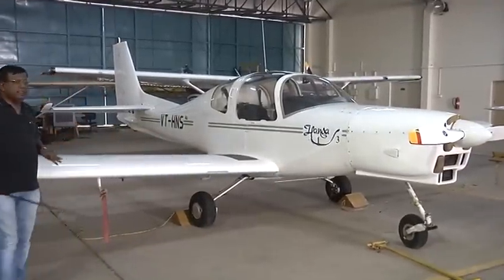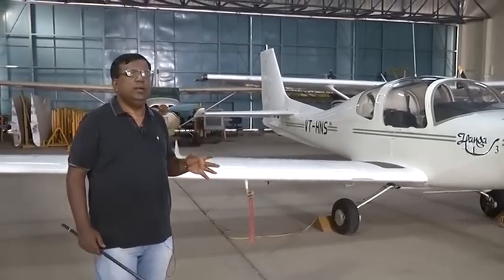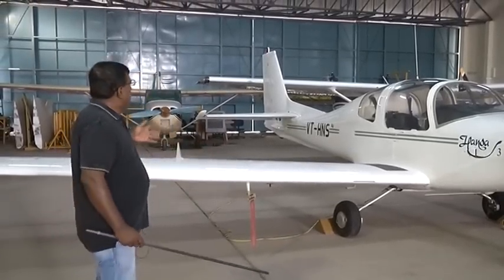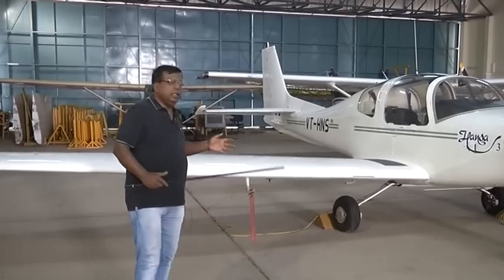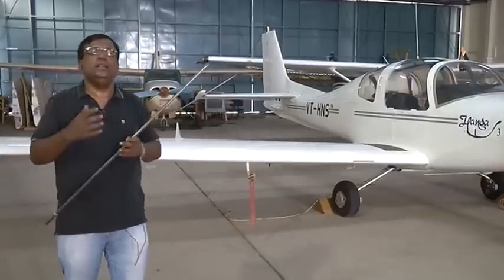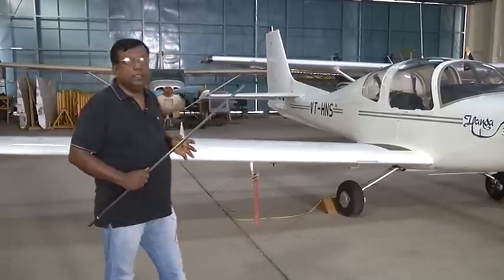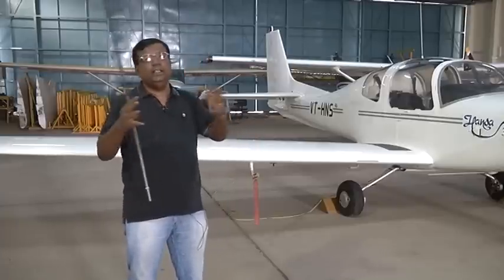But when I am talking about forces separately on the fuselage, on the wing, on the horizontal tail, and trying to add them with a lot of care that I know there is an interference effect, right? This method is called the component build-up method. That is, you find out the component and then add.